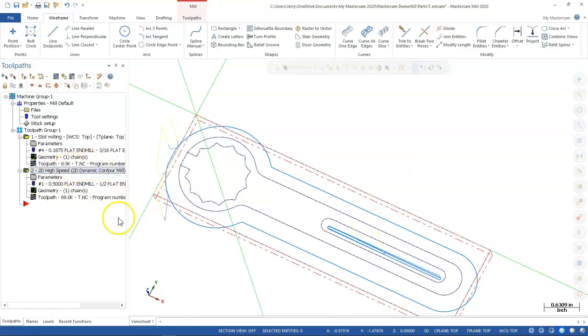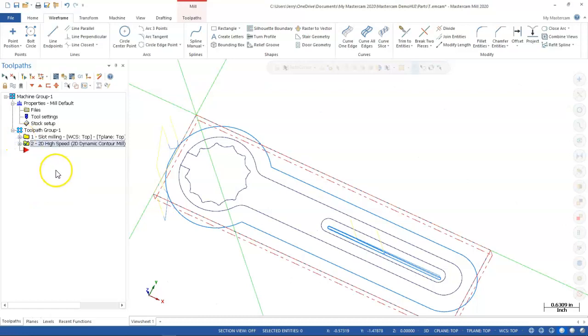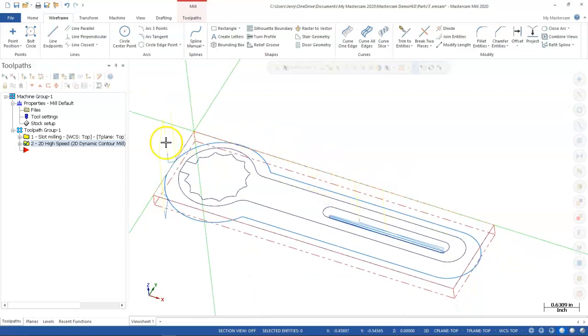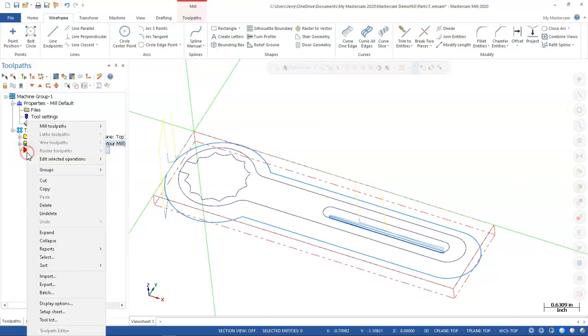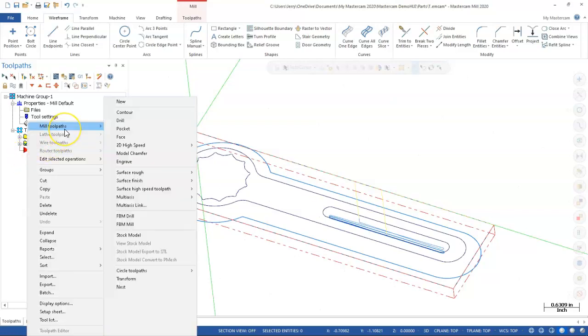But again, we can go back. If it takes it fine, it's only 1/8 of an inch deep. It's a full width pass. We're not real aggressive on our feed rate. We'll see what we get. All right, so you can kind of play with those numbers. The other thing was in our standard contour, we would look at the trochoidal cuts, which would do a lot of extra moves and could really elevate the feed rate. We just have to kind of play with those and adjust accordingly. All right, one more, and actually two more.